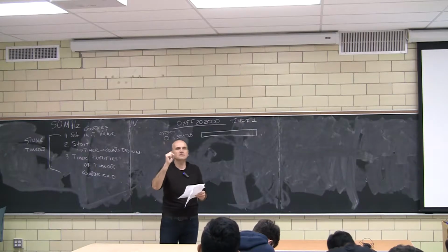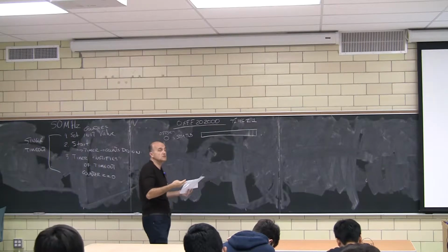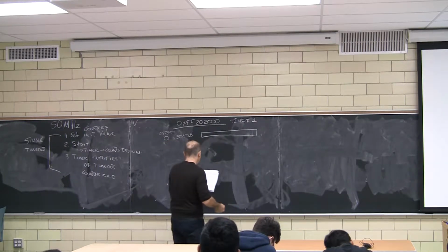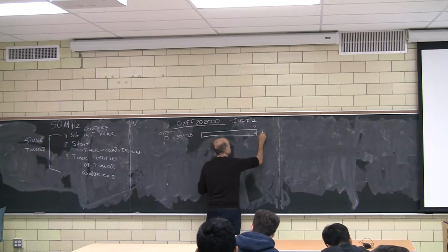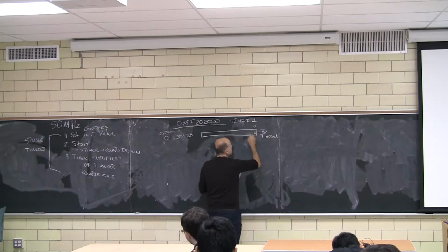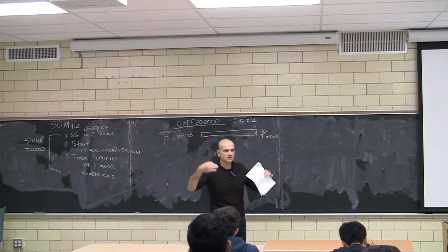That is, think of them as light bulbs. They turn on, meaning something. You can write to this register, it has no effect. It's meant to be read only. Okay. So bit 0 is TO, which stands for timeout. In the beginning of time, this is supposed to be 0. The moment you ask the counter to start counting down, it remains 0.